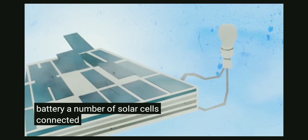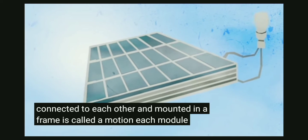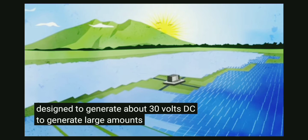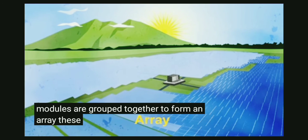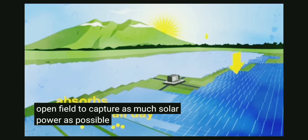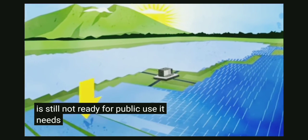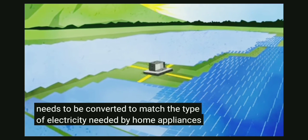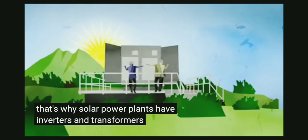A number of solar cells connected to each other and mounted in a frame is called a module. Each module is designed to generate about 30 volts DC. To generate large amounts of electricity, modules are grouped together to form an array. These are scattered throughout an open field to capture as much solar power as possible. But this electricity is still not ready for public use. It needs to be converted to match the type of electricity needed by home appliances. That's why solar power plants have inverters and transformers.